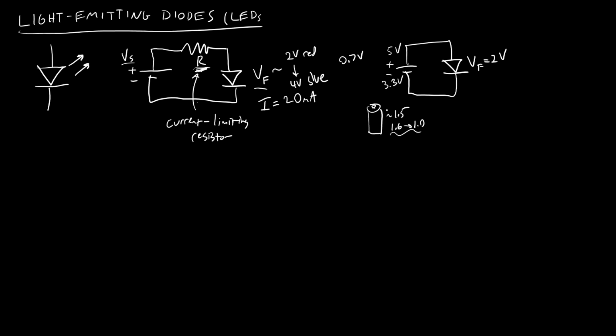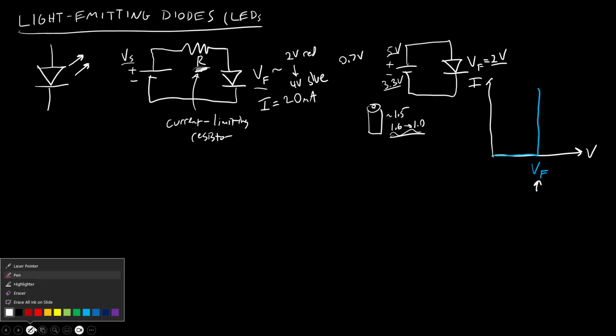For common circuits, either wall powered or battery powered, you might not have something that is the exact voltage that you need for your LED, or that voltage might change as the battery drains, so you're not going to have exactly what you need for your LED. And then second, remember that the idealized diode model, we treated it like this, okay, we just have this perfectly constant forward voltage drop on an IV curve. So we say, oh, that's exactly the voltage drop I need across my LED.